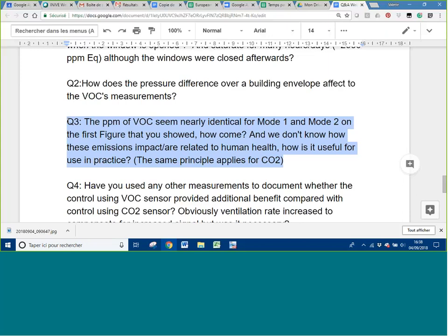We were dealing here with flow rates of about 50 cubic meters per hour for space. So yeah, again, all it does is provide some extra fresh air at the moment where a peak like that occurs. And if you analyze the data a bit more carefully, we could see that this makes the high peak still occur, but it is ventilated away faster. So the decay is faster after the peak.